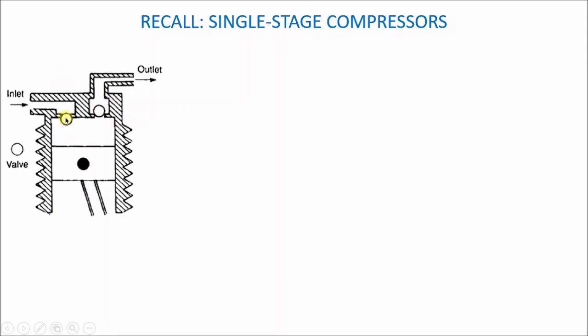And the inlet valve will be open. And so the piston is then going to move down inside of the cylinder until it reaches the bottom dead center, which is the lowest position that the piston can reach inside of the cylinder. And because the inlet valve is open, as the piston is moving down like that, it will behave more or less like a syringe, and this will suck in air through the inlet duct as the piston is moving down. And this is how you fill in the air inside of the cylinder.